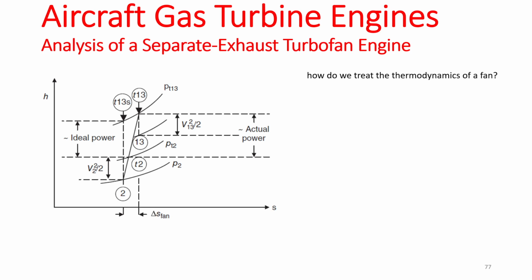Okay. I think the compressor, because when the fan takes in the air, isn't the air afterwards heated up and mixed with gasoline? Or is that... In a turbofan, no. There's no combustion in a turbofan. There is a combustion inside the core of a turbofan, but there's no combustion in the fan, right? It just takes the air in and gives it out. You were talking about afterburners, so I thought... No, that's for a mixed exhaust. We are not doing mixed exhaust here. We are doing separate exhaust.